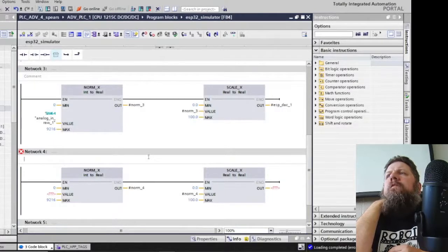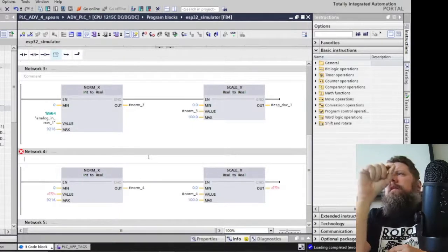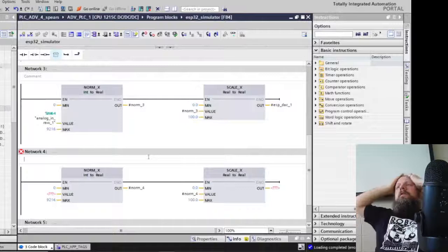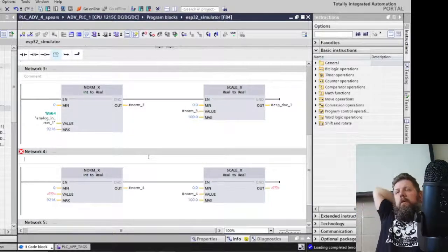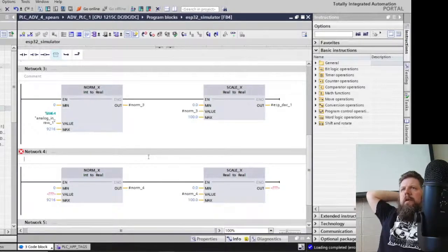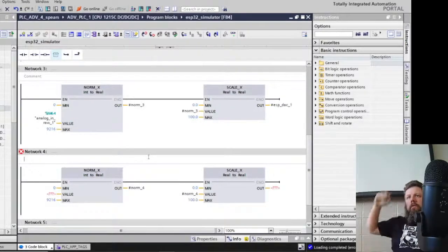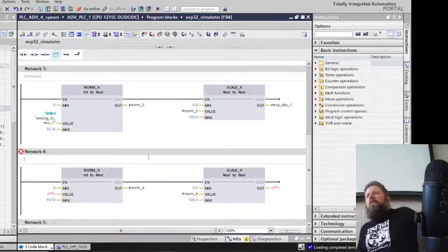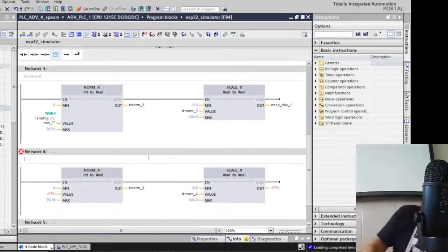But what's the difference between 9.4 and 9.5? If I do that, then there's no difference. If I do it with the 0.0 behind it, then with that little bit of 1/10 of a place, now I got 1,000 different discrete steps, right? I can get more resolute, because I can tell the difference between a 9.4 and a 9.5.